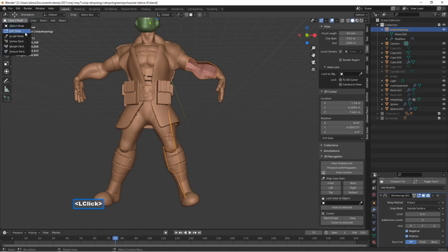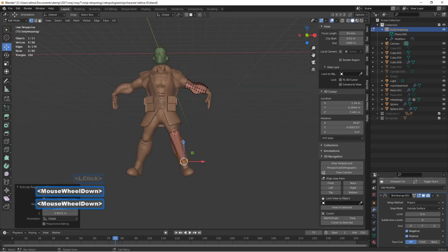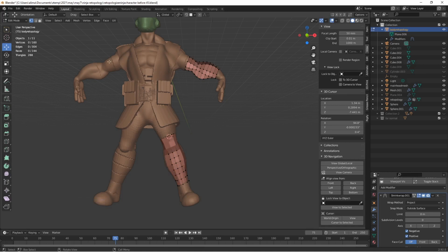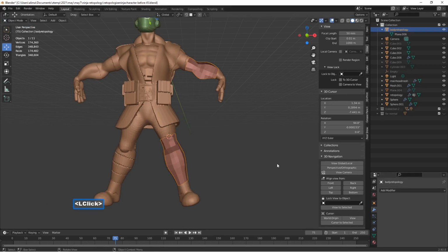Go to the upper left, go to edit mode, and then similar to before, we'll press E to extrude, bring this down, roll the mouse wheel to zoom it back. So with that there, now we'll hold control, similar to before, press R. So we'll include that as the first loop cut. We want to take this up to 8, so it's 2, 3, 4, 5, 6, 7, 8. Then we'll left click to lock that in, left click a second time to lock that in, left click to deselect, go to the upper left, go to object mode, go to the arrow and shrink wrap, then select apply.